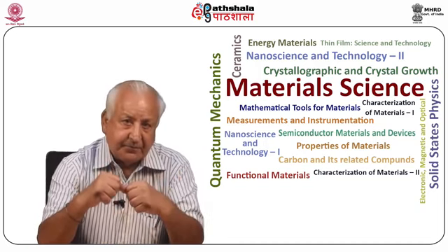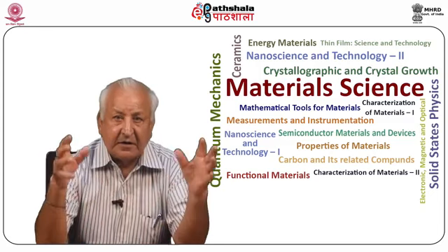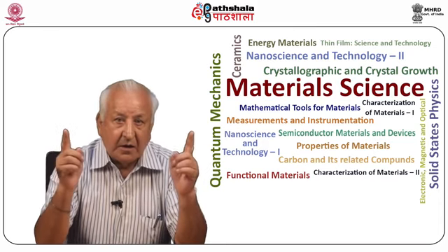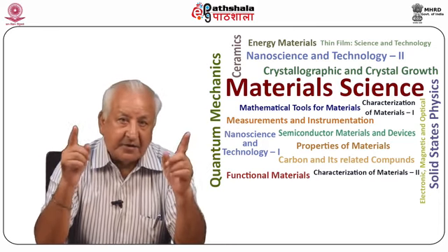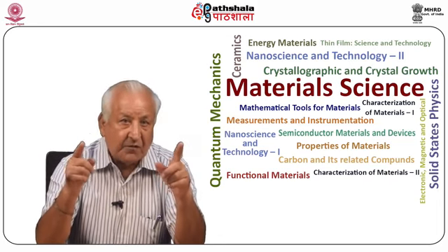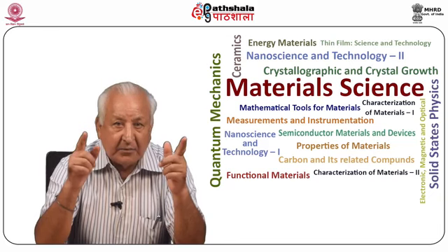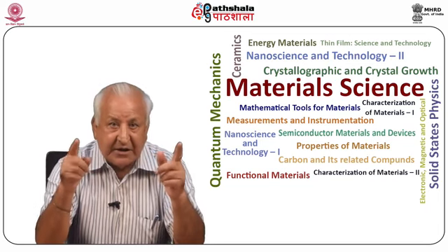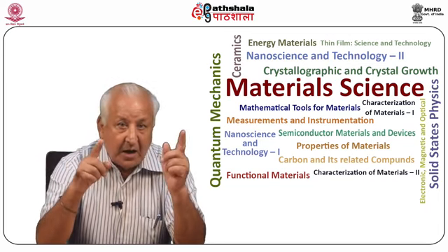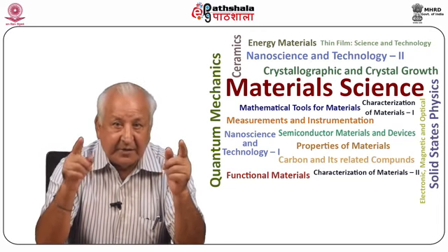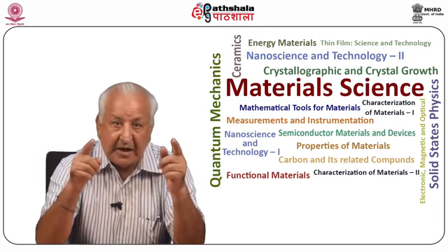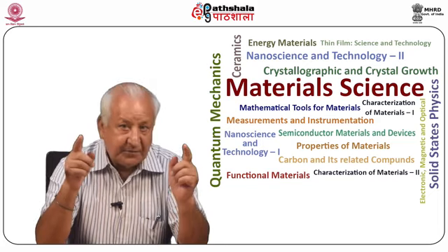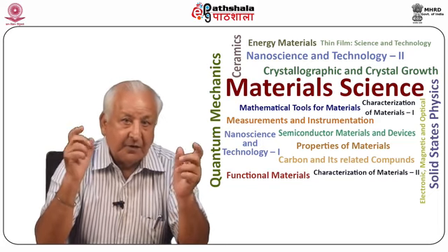The electron injector consists of a heated filament, capital F, which acts as a source of electrons; a grid, symbolized by capital G, which is used for focusing electrons; and a plate, represented by capital T, which is used as injector shield. High potential difference is maintained between capital T and capital F so as to send electrons at very high speed into the vacuum tube, VV.